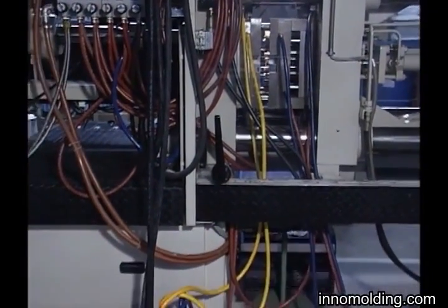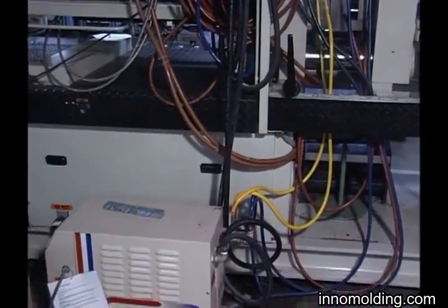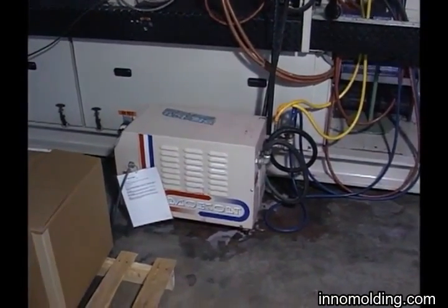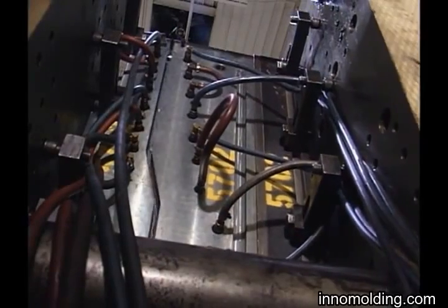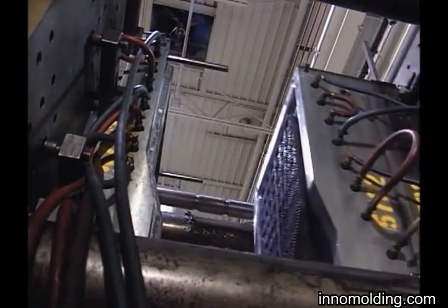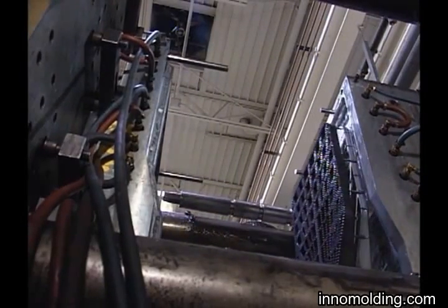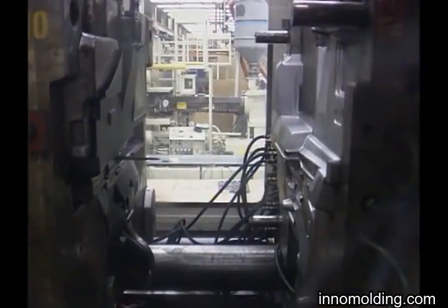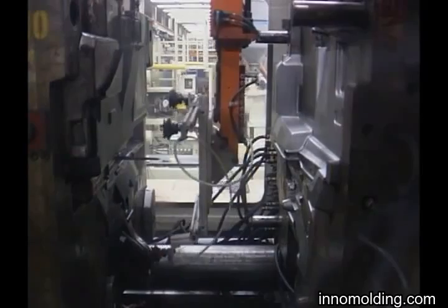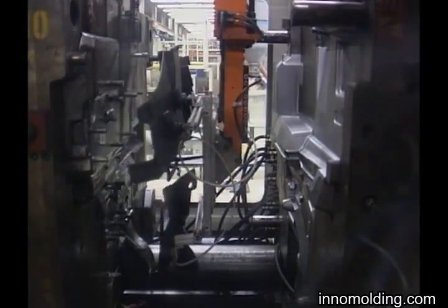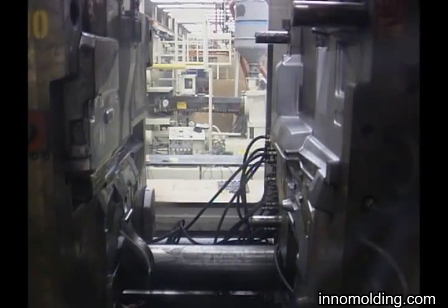Built into the mold are channels for circulating water, which is the mold's primary cooling medium. The water is pumped continuously through the mold to and from a cooling unit, removing the heat and solidifying the part. Proper cooling provides a consistent temperature and coolant flow rate, which contributes to controlled shrinkage, part strength, and other properties. The speed of the injection molding production cycle is controlled by the efficiency of this cooling system. Aside from producing acceptable parts, efficient cooling is the most important factor of the injection molding process.